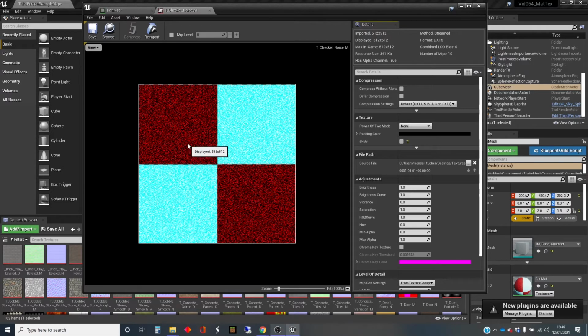And that's all very well for the actual points themselves, but what the rendering does is it works out all the other points in between that we haven't provided information for. It does what's called interpolating. And so if you have a point on the surface which is meant to be somewhere around here, as long as you've got some points set up with the right UV coordinates, it will work out how far across it needs to be from those points that it got. So it triangulates it inside whatever triangle you've got and works out what point in the texture should be applied. And then it does what's called sampling, which is it picks the colour for that particular point out of the texture.